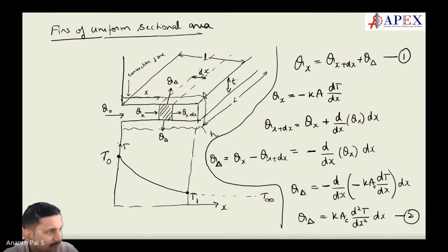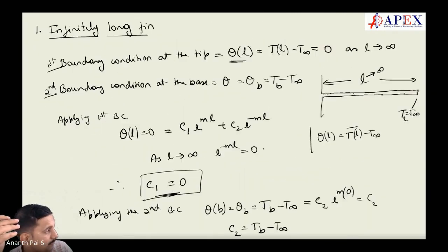Yes, very much. But then there are cases where circular is the best. Circular will become cheap. It's always economic. It's not just heat transfer only. Along with heat transfer, economy also matters a lot. If you get small rods easily and cheap, you use it, is it not? Instead of making a complex shape, which will take a lot of effort, manufacturing time and manufacturing cost. So if something is manufactured at a low cost, you can use it. So engineering decisions are not just based on one criterion. There are a number of criteria which come into the picture: ease of manufacturing, assembly line, then maybe vibrations. A lot of things come into the picture.